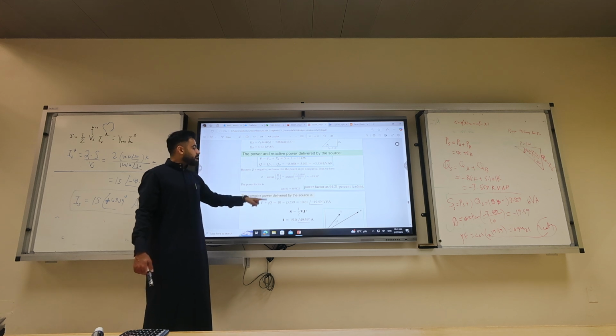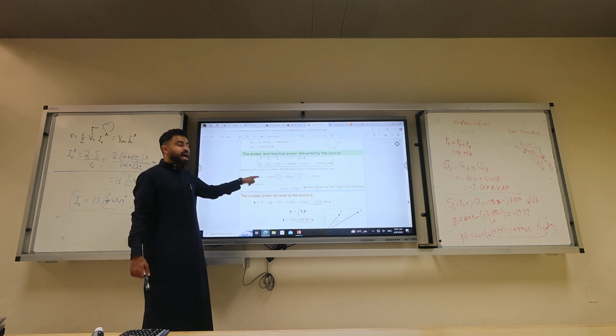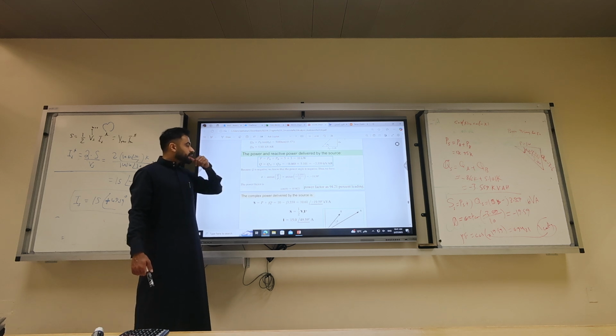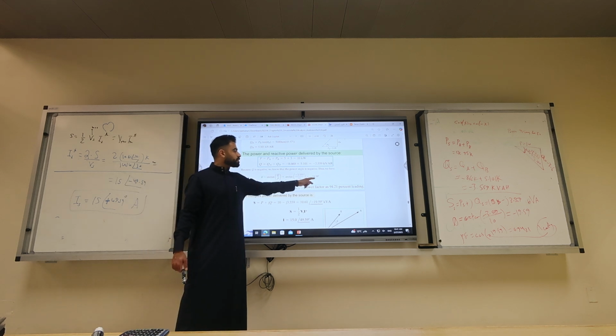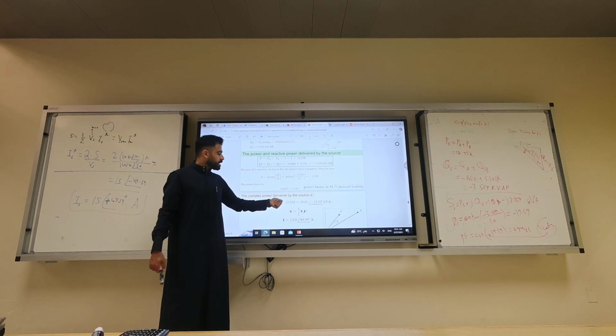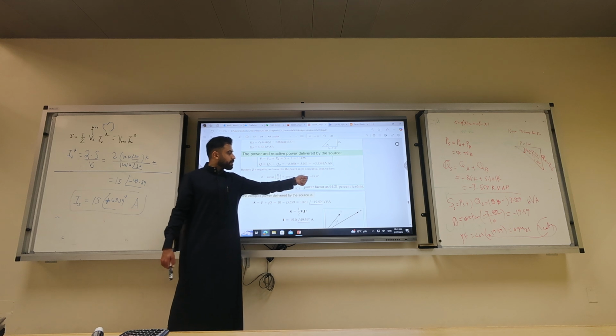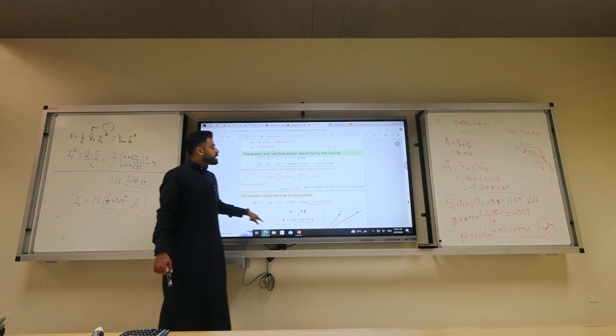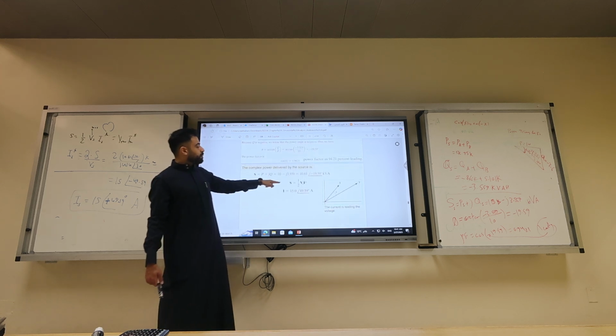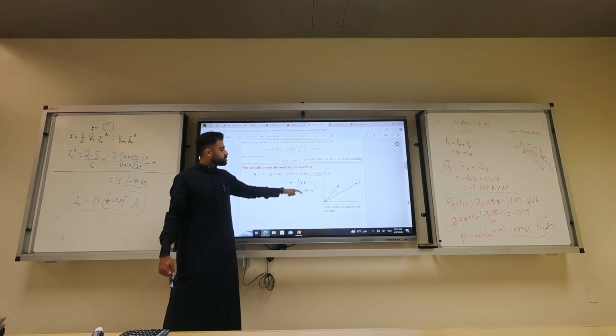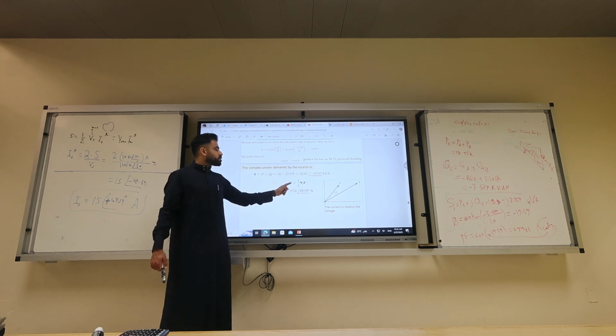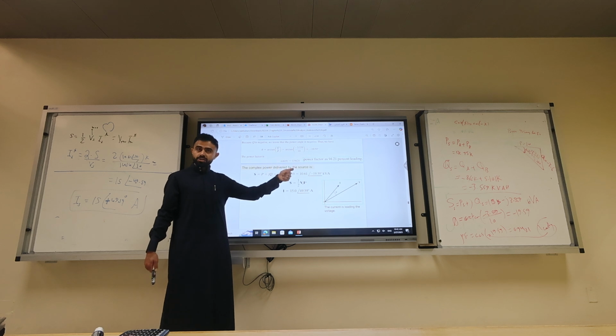Not only that, I also need to calculate the angle of this number, which is minus 19.59. We take basically Q over P. So we got the number minus 20 degrees. Then I use that formula, S equal half VSI conjugate, to calculate I. So it's 2S over V, that's I conjugate.